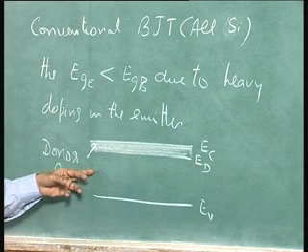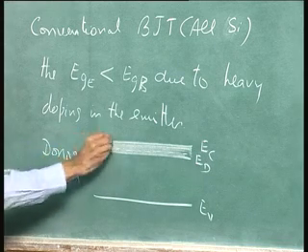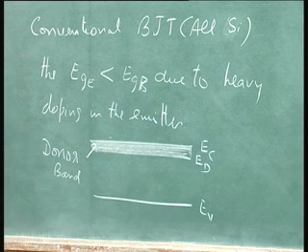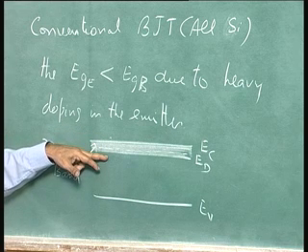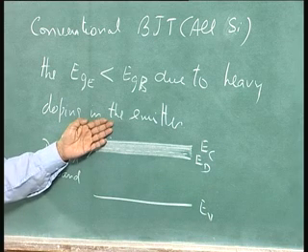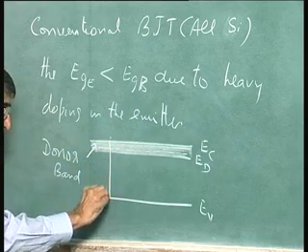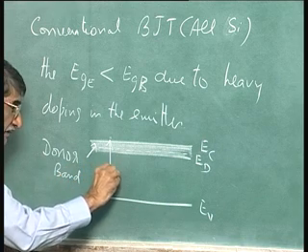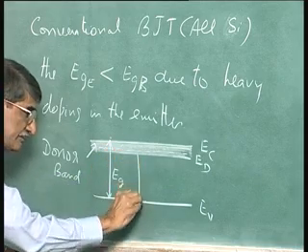Now, you can see what happens is, if this is a discrete level, that is a conduction band edge. Now, the donor level has split up into a band and merges with the conduction band. There is no distinction between the conduction band edge and this level now. In fact, you do not get any carrier freeze out effect, etc., because all these electrons are in communication with the conduction band. Okay. Now, the Eg, that is supposed to be the Eg. Okay. But the effective band gap is that.